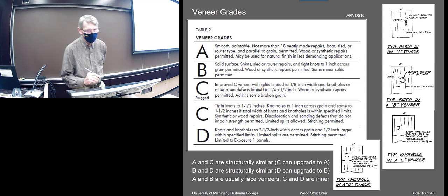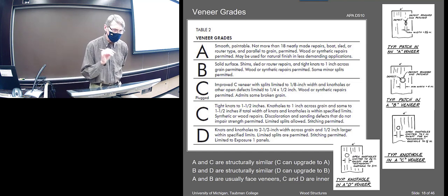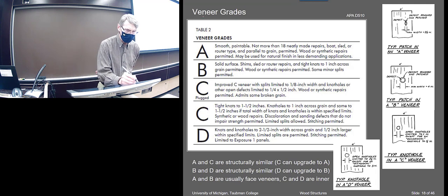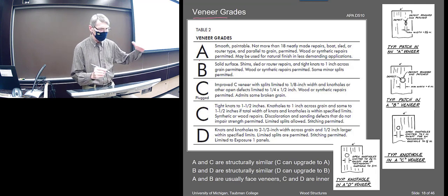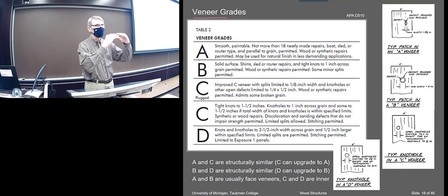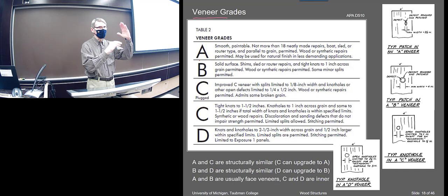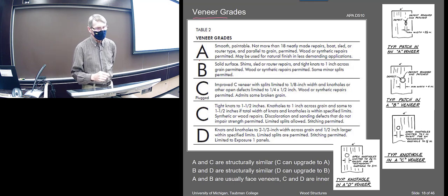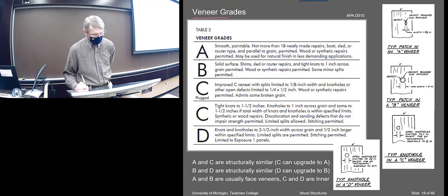Then in addition to the group, it gets a veneer grade, right? And the veneer grade is, you've probably seen these, A, B, C, D, and then they'll sometimes have a different grade for front and back, so it may be like AC, together like that.